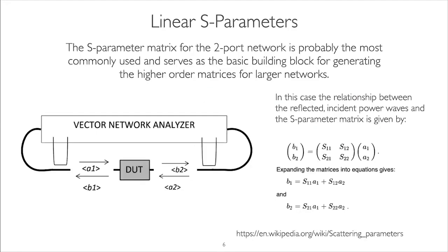So again, if you've attended one of our previous webinars, we've talked about linear S-parameters, load pull techniques and whatnot. I'm not going to spend much time on this, but one important thing to understand is measuring the A and B waves of a two-port component using a VNA. So basically we're going to be using this architecture to measure A and B waves coming out of a device, and based on this information, we'll be able to adjust the signal that we're re-injecting back to the device.